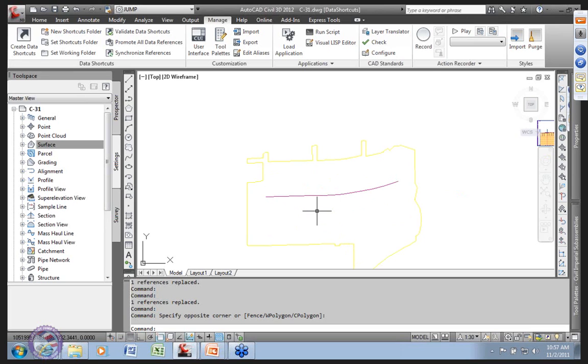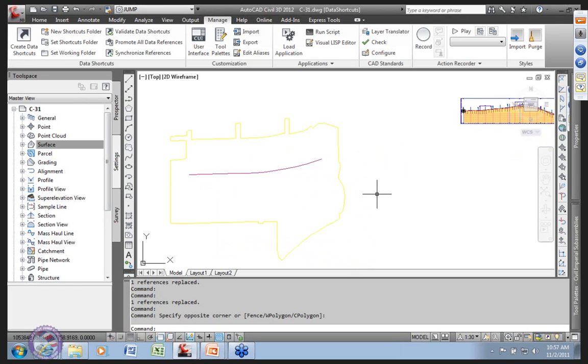And why would I want a drawing completely in standard? Well, being completely in standard means that it will upgrade without issue. So AutoCAD Civil 3D's code will actually create standard placeholders where it needs to, for almost all, let me say almost all, features and their label styles that are required. There are some sets it does not.